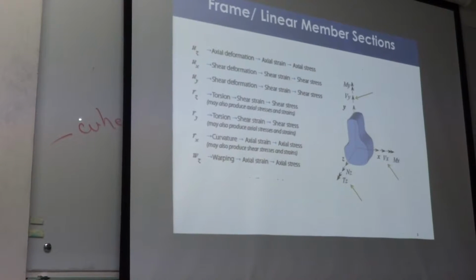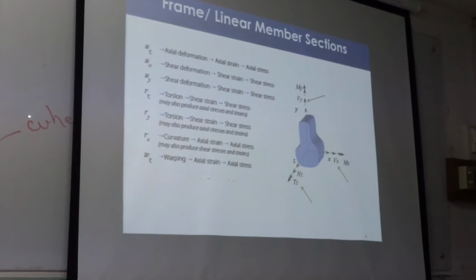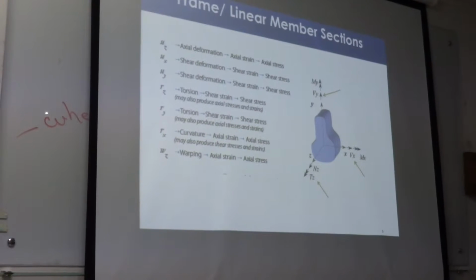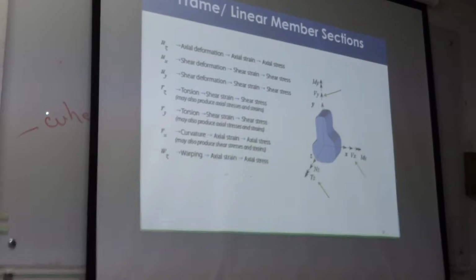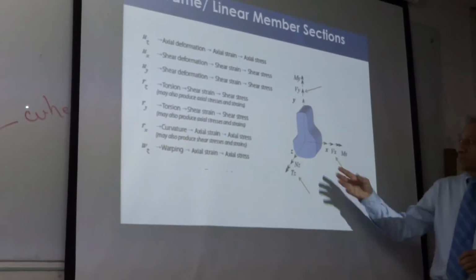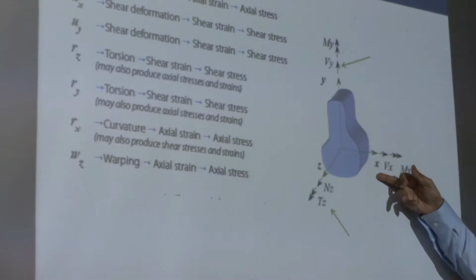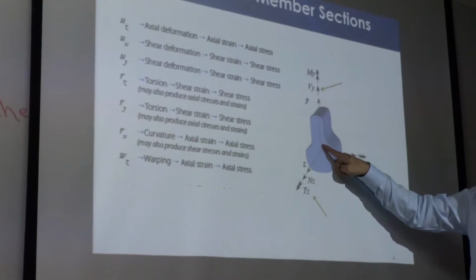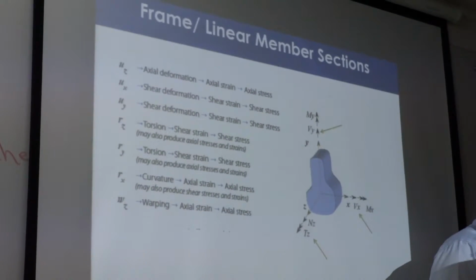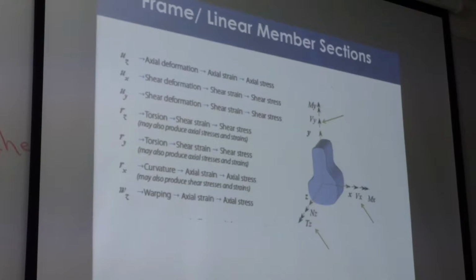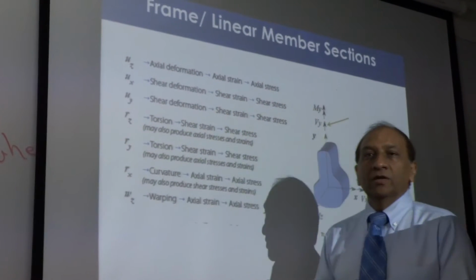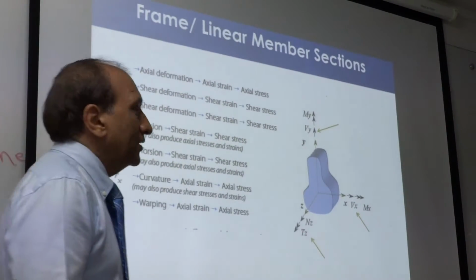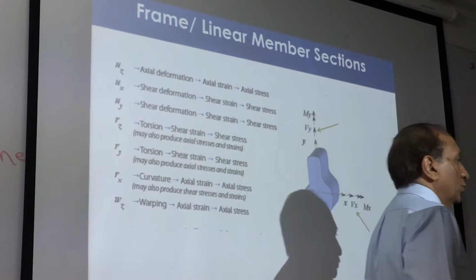Normally when you do beam design, you only deal with one shear, which is the shear perpendicular to the direction of the loading. But because last time we said that we will not distinguish between beams and columns, every cross section can have shear in any direction, just like moment. But we can have two components, one along this way, one along that way. One we normally call major shear, and the one we will call minor shear. So we will be dealing with both the shear design, because in columns both shears are possible and present. In fact, mostly the shear is inclined and we have two components.